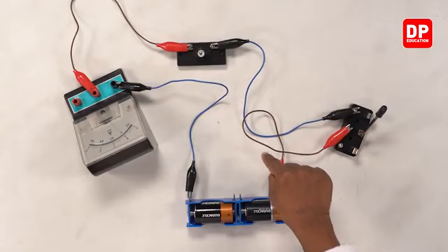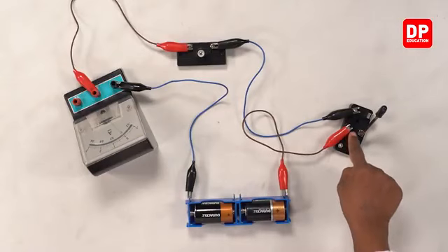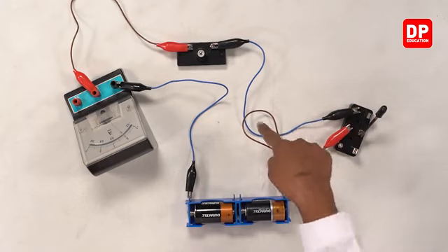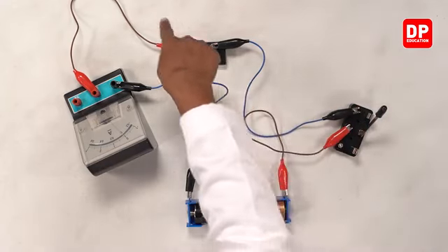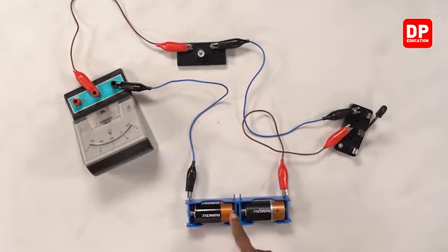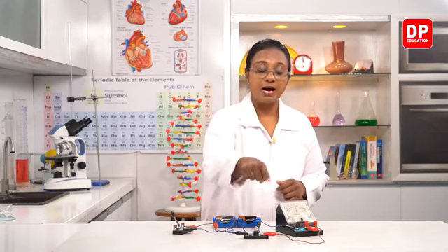Now in this circuit, you can see, students, the current flows through this red color wire to the terminal of the switch. From the other terminal of the switch, you can see there is a connection to the bulb. From there to the ammeter, again back to the dry cell. So it is flowing continuously. This type of connection is known as a series connection. Now all the current that flows through the bulb flows through the ammeter. Then only you can measure the current flowing through the bulb. That is how we are supposed to connect the ammeter. It is known as the series connection.